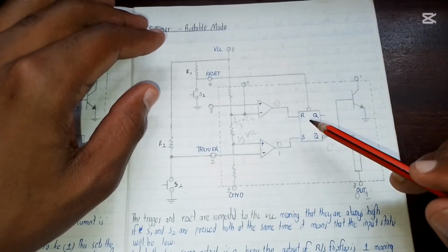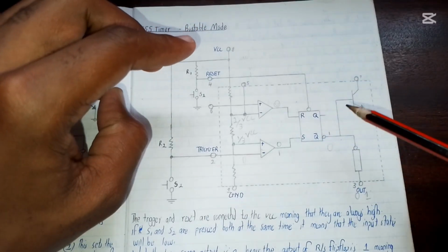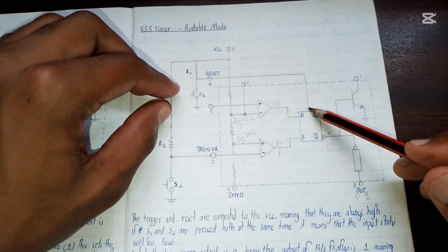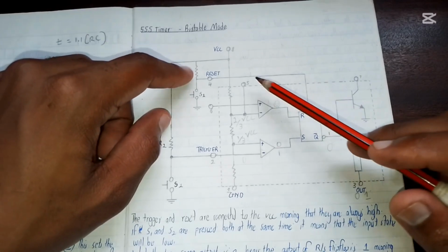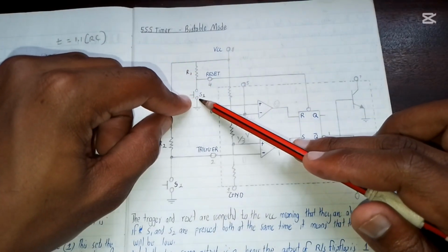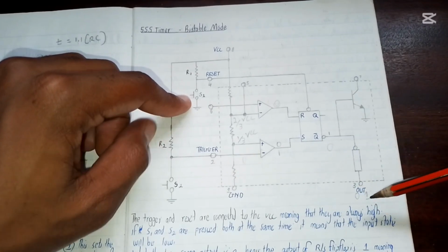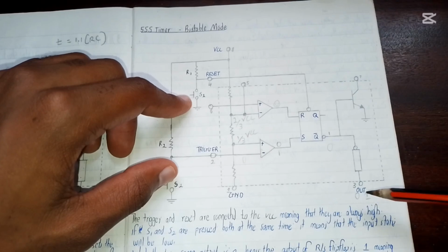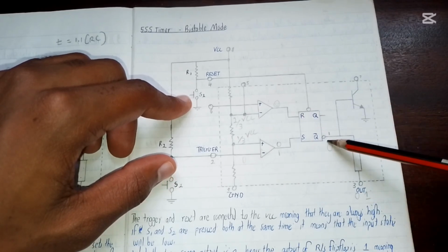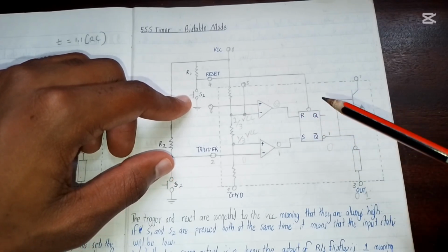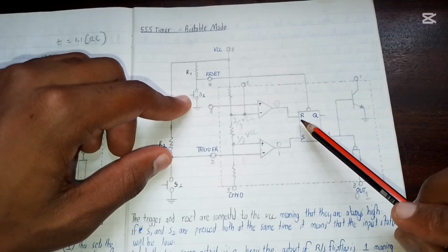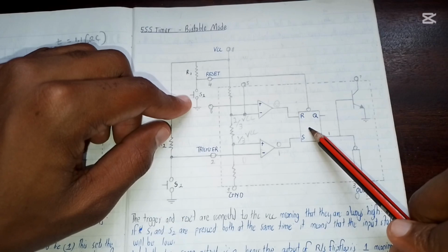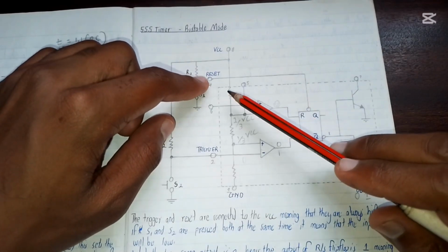So the only way to change the values, or the only way to change what you have at your flip-flop, is to press this reset pin, and that's why we have connected it to this other switch. So the output will be remaining on even if you press this switch. It won't change the value of the output. The only way to change the value is by clearing all data that is recorded by this flip-flop. So the only way to do that is by pressing this reset pin.